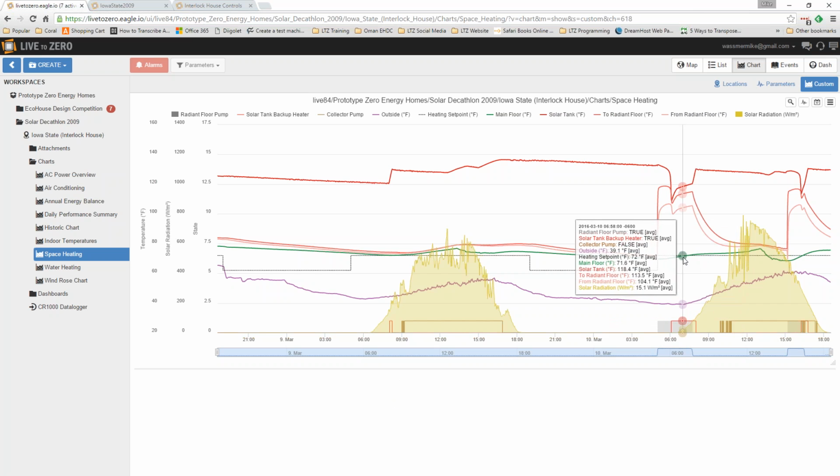And the benefit, because you could see at 8 a.m. when they showed up, the building was at 73. It was already starting to overheat. But the temperature would not have been 73 at that point unless we turned this heat on. It probably would have been maybe 70 or 71, which technically is cooler than what the occupants said they like.